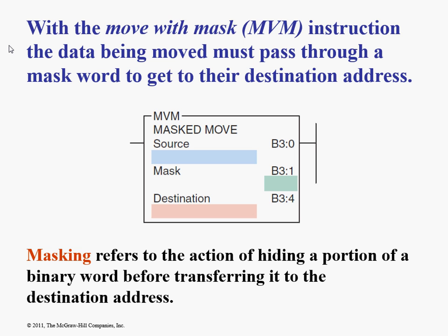Well, you probably don't hardly anymore, but remember how I told you how old barcode scanners or a thumbwheel switch work, and how we hooked to like 4 inputs and got a binary number? Well, if we had an input card and we used the first 4 inputs for a thumbwheel switch, then we could mask that data off and use the rest of the input card for actual push buttons or sensors. We can mask the data coming off something. So it's pretty easy to see that.